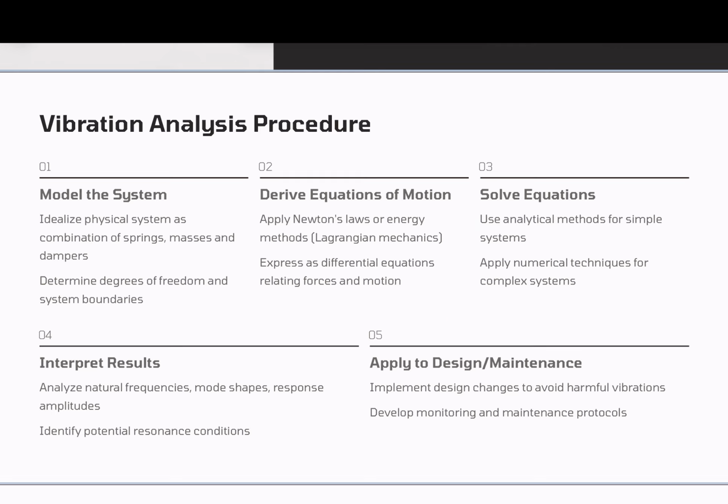Fourth, interpret the results. After solving, we interpret the results. We look at important characteristics such as natural frequencies, the mode shapes, and the response amplitude. We also check for resonance conditions, because resonance can be dangerous if not controlled. Finally, we apply the results to design and maintenance.